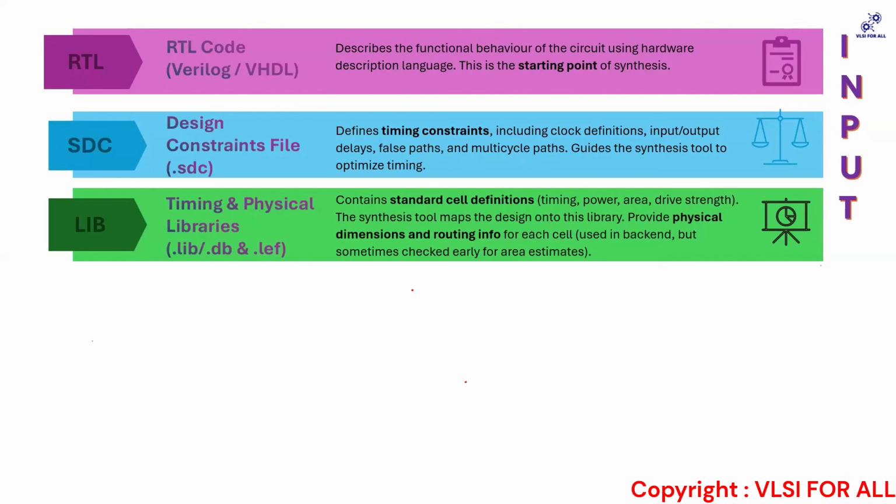The advantage of swapping with VT is that your footprint remains the same. There is no change in the size of the cell. You can also guide the tools with a lot of constraints, such as telling them kindly not to use certain cells. You can give it through the don't touch cell list.